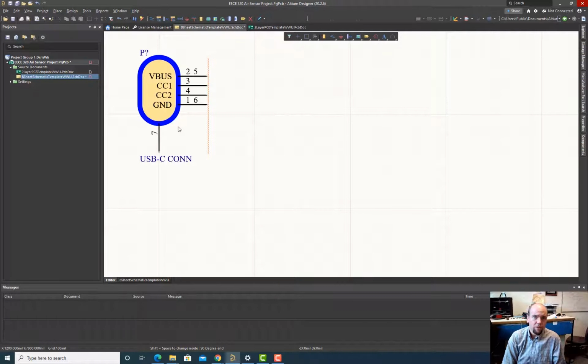So we're not going to worry too much. We're just going to connect the shield to ground, which is a fairly common practice. If you were doing a different design that really had to be protected against potentially high current static discharge events, you might have it connected through some sort of electrostatic discharge suppressor circuit. We're not getting that fancy though. We're going to keep it simple. So, but this is 7.